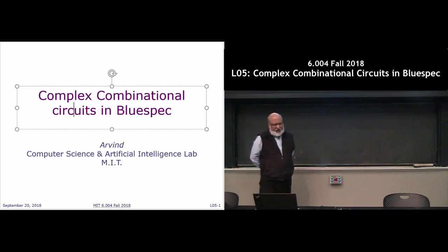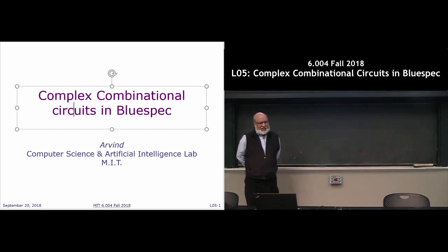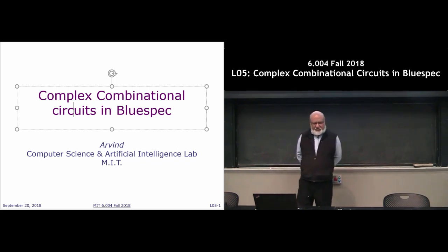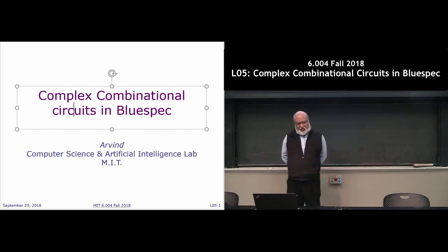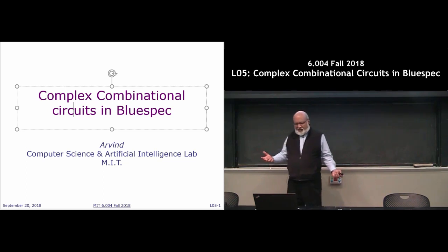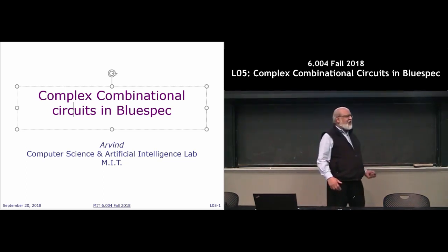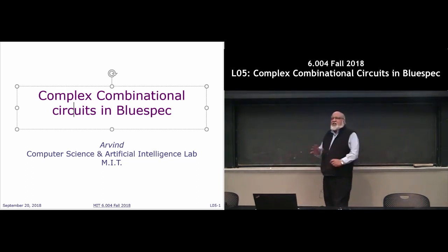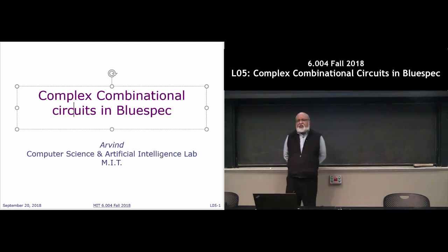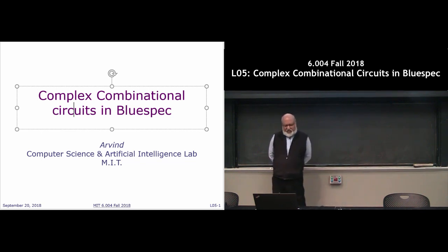All right. So type synonyms is another thing which we define very liberally. So I write typedef Bit#(8) Byte because I use it so often. I call it a Byte. Remember, Byte is written in capital because it's another type being defined, right? Word, I can call Bit#(32), and this is up to me. There's nothing built in. I can define it any way I want, right? Tuple. So here is a Pair. What does this say? Why am I writing Pair?